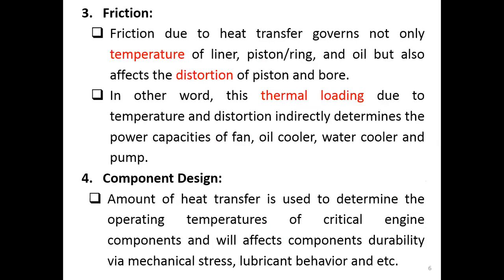Okay, so this is the impact on the exhaust. How about the impact on friction? The heat transfer impacts the friction. Friction due to the heat transfer will govern not only the temperature of the liner. What is the liner? The liner is some coating that you have on the cylinder surface, or it may be a sleeve that you place on the surface of the cylinder. It can be either one of these.